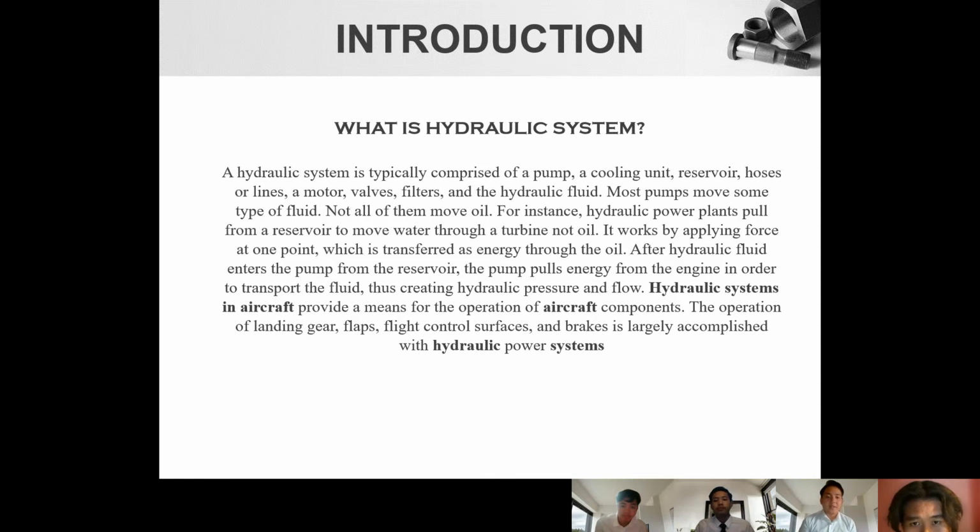After hydraulic fluid enters the pump from the reservoir, the pump pulls energy from the engine in order to transport the fluid, thus creating hydraulic pressure and flow. Hydraulic systems in aircraft provide a means for the operation of aircraft components. The operation of landing gear, flaps, flight control surfaces, and brakes is largely accomplished with the hydraulic power system.